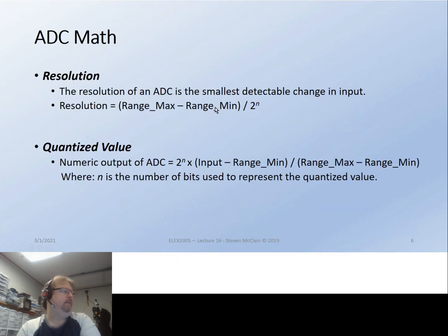That actually can be assigned. It's automatically 0, but you can change it to something else. You can also feed in external voltage references and all kinds of other stuff. It slices, it dices. Okay, and the reason for that would be what? Say you've got a temperature sensor that goes from 2 volts to 2.5 volts. Oh, okay, so you never actually go below 2 volts. So in that instance, you would just make your range min 2 volts.